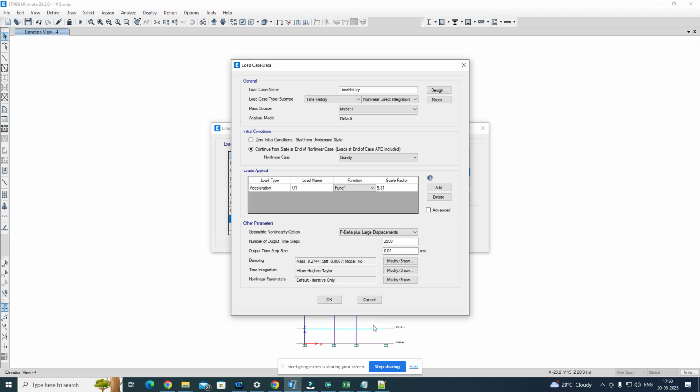Now if you select those ground motions and analyze the structure without any matching, it will not be fair to observe anything from that analysis, because that ground motion may not be reflecting your site, right?